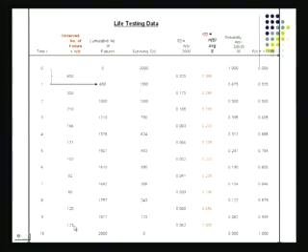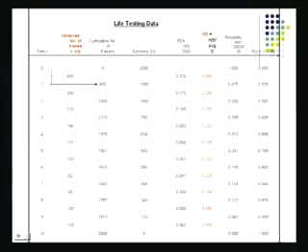Now this, if you can actually see, is kind of like your bathtub curve. Initially you've got it coming down, then it becomes somewhat flat, then it begins to rise again. You are able to see this bathtub curve there. And then I show here the different columns. If you come toward the end of the table here, you'll end up finding the reliability, and you'll notice reliability tends to become flat and low at a certain point in time. This is something that you can see very, very easily.